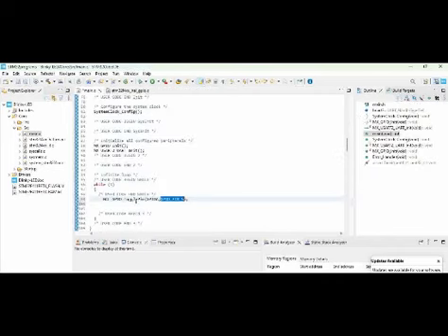So that means the PA5 pin is configured here, and there is an inbuilt function in the HAL which is HAL_Delay. Let us try to use that. Whatever value we put here, this will create that many milliseconds of delay. That means we are creating 200 milliseconds of delay. So here we are first toggling and then waiting for the delay, then toggling again.